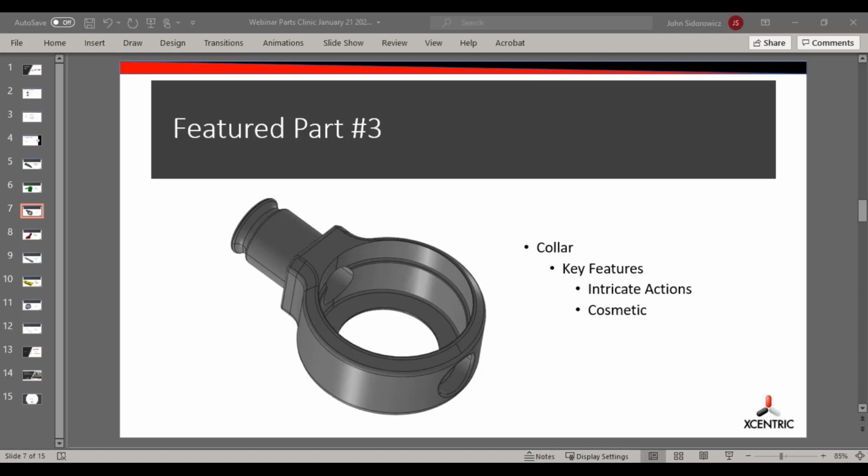All right, while you're doing that, we did have another question. Was injection speed fast to keep the insert position? To be honest, it likely was not. We probably slowed it down a little bit, at least initially, to see how that component flexed or moved, and then made adjustments accordingly. The material sometimes dictates the speed at which we are allowed to inject the plastic into the tool.